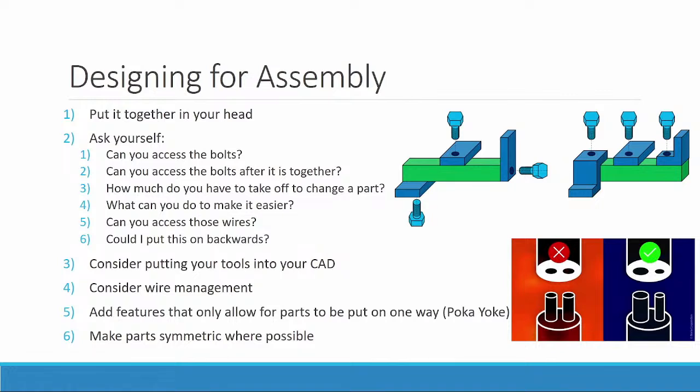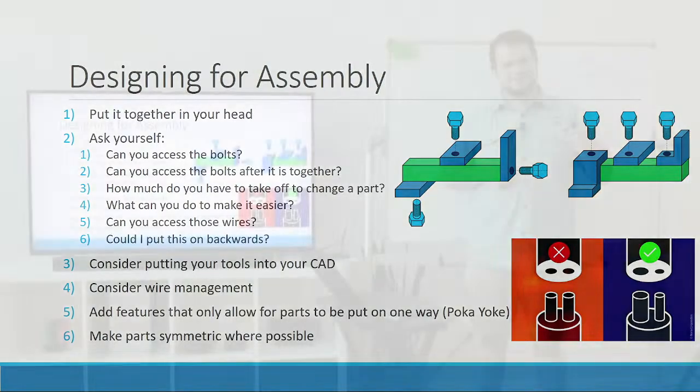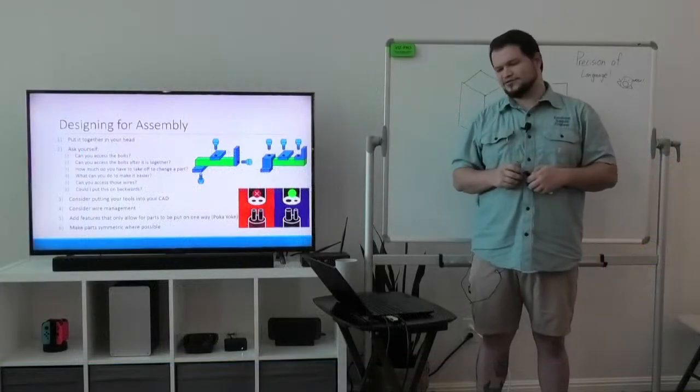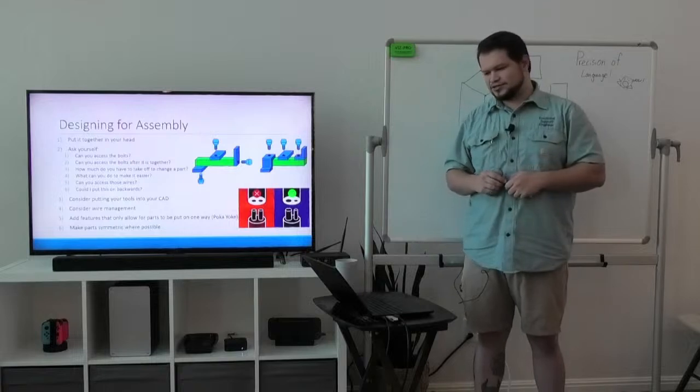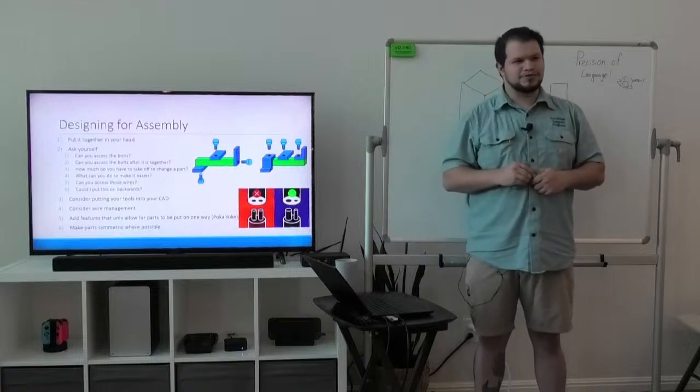When you are designing, the best thing you can do after you are done is say, okay, how would I put this together? And go through in your head, step by step, what would you do to put it together? Well, I'd put this U-channel first, and I put this, what is it called, quad block here, and I put a screw in there, and then I put the motor in, and I put the screws in for the motor. And once it's all put together, you should ask yourself, can you access those bolts?